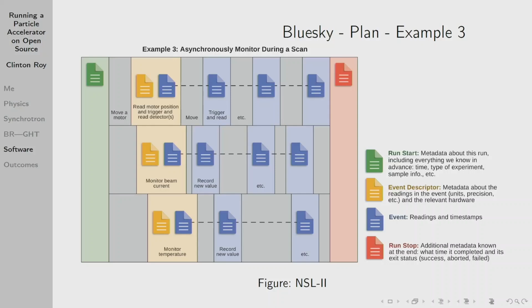And down the bottom there, we're monitoring temperatures. On the BioXAS beamline, we've got like 40, 50 temperature sensors. If anything happens to the focus of the X-rays and the X-rays veer off where they're supposed to be going, they'll hit a bit of metal. That metal will heat up and one of these temperature sensors will go up. Very quickly we'll get an alarm and we'll figure out that something's wrong and we can close the shutter and stop the experiment. That's very much a safety thing, but it also means that if we get a temperature spike somewhere, the X-rays are not hitting our sample, they're hitting one of our shields, and there's no point keeping going with the experiment.